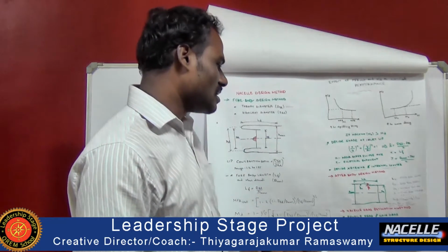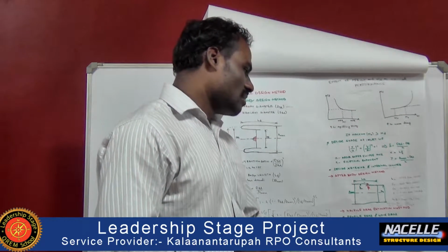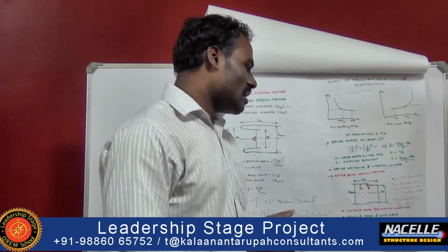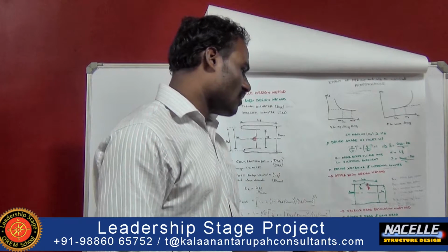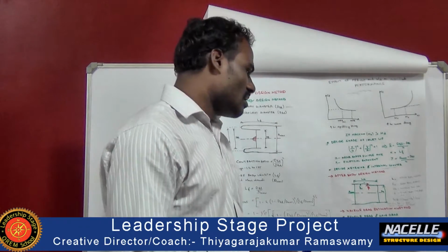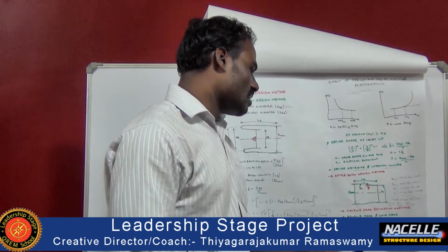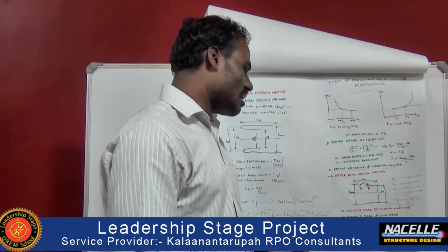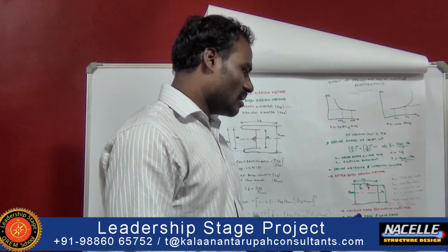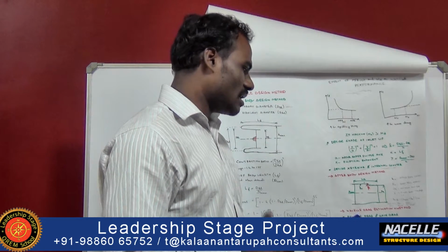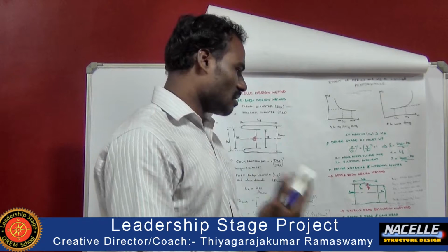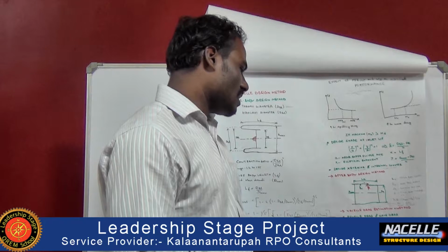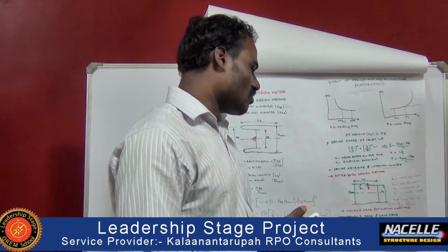In the on design condition, if the Mach number is within the limit of critical mass flow ratio and the drag ratio, it leads to a profile drag, which helps us in the better performance of the engine. Whereas in the off design condition, if the Mach number is outside the critical mass flow ratio and the drag limit, it leads to spillage or wave drag. Based on the design procedures, the nacelle drag is classified based on the performance with respect to the profile drag or wave drag.